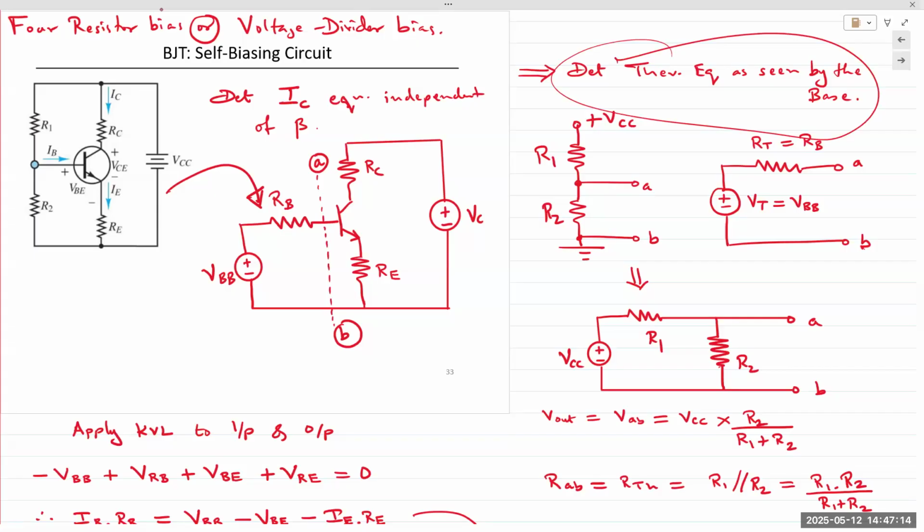Okay. The beauty of this circuit is that we can use one single supply, and that one single supply biases the collector side, and it also biases the base side of the input. And so by using a voltage divider bias on the input side, we can use the exact same voltage that is on the output. Yes.